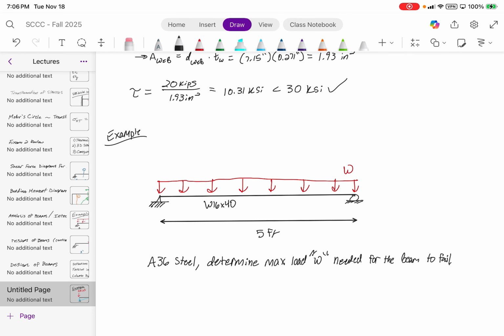Well, where are you getting these values though? No. I'm asking you what the maximum value for W is. 40 would just get added on. But you can ignore the self-weight on the beam, guys. All right? Nope. The entire problem is asking you what is W, which means you don't know the bending moment, you don't know the shear force. You only know how the diagram roughly looks, which is this. All right?